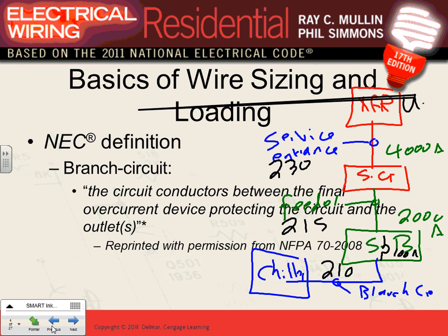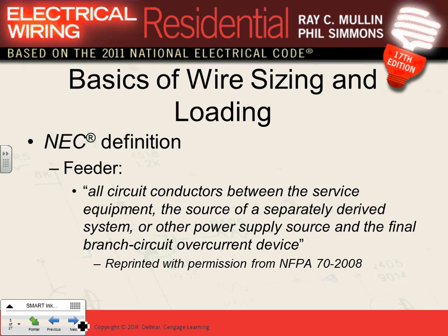I'll show you later on, guys, a hospital one-line diagram that has almost 100 panels in the emergency system as well as the normal system. So there are so many panels in this area. Down here are your loads. This is very important, guys, as a designer, to understand the flow of energy inside your building. Everybody's okay with this? So how the system is put together. I can't take a branch circuit from the transformer, right? You have to go through this sequence, with different protections at different spots.